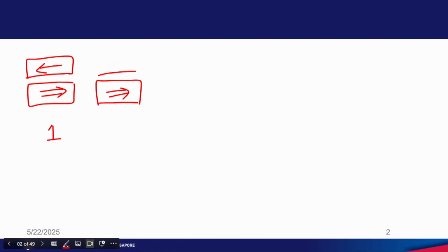The reference layer magnetization is always fixed in one particular direction. So writing 1 means making the free layer magnetization anti-parallel to the reference layer. Writing 0 means making the magnetization of the free layer parallel to the direction of the magnetization of the reference layer. Okay, so this is basically writing. Since we are switching the magnetization, we also use the terminology switching to represent writing information.